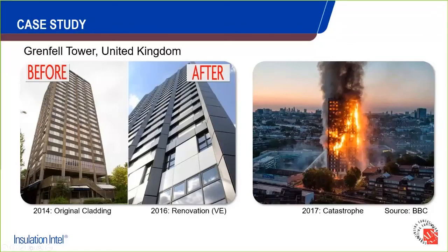So this cladding system, there were two types used. One was an aluminum composite metal, basically aluminum sheets with a polyethylene core, and the other had a polyiso core. I don't know exactly which areas of the building had which, but I do know that the polyethylene is the most flammable of those materials.